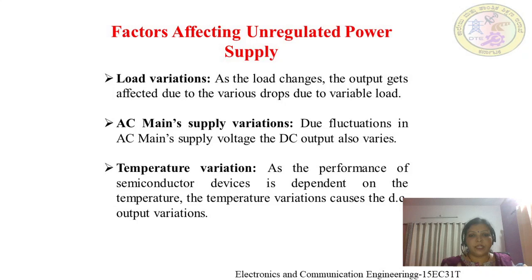It should not increase; it should be able to provide a fixed voltage. This problem generally occurs in an unregulated power supply. Therefore, we should have a DC regulated power supply.